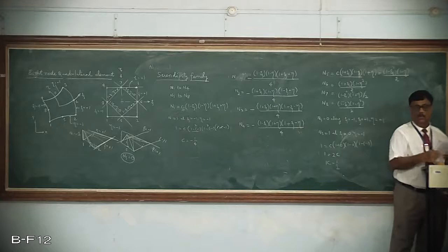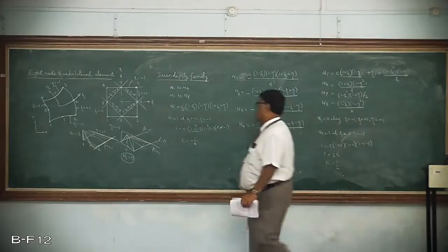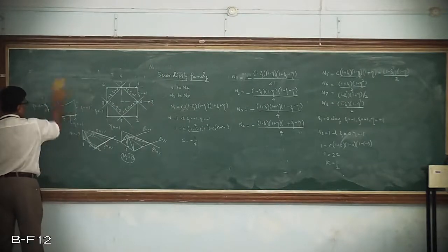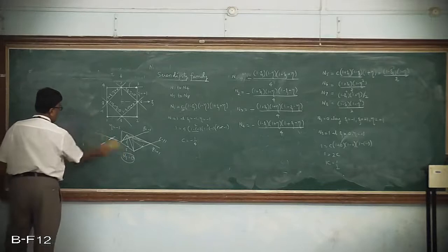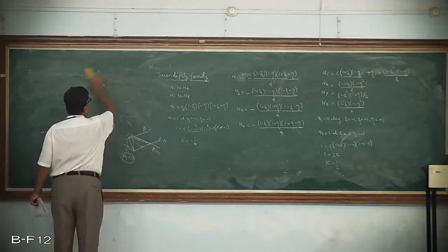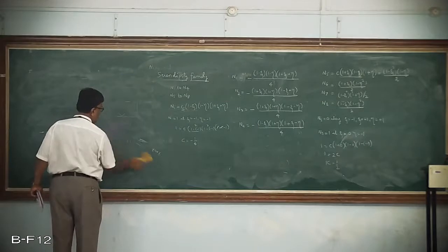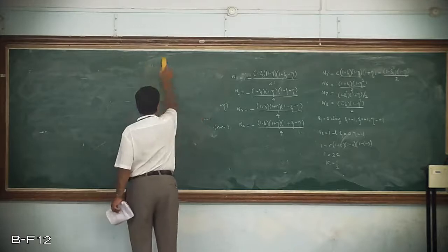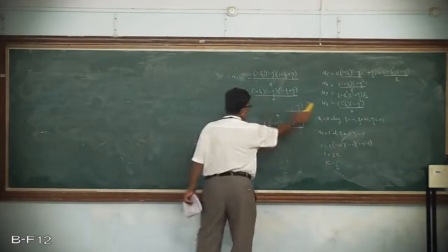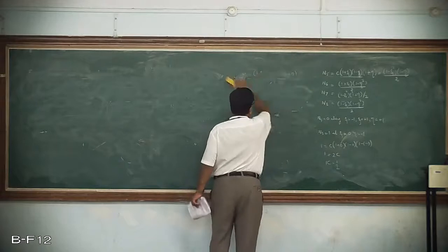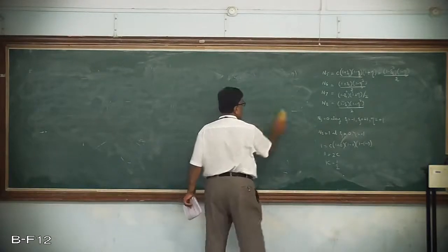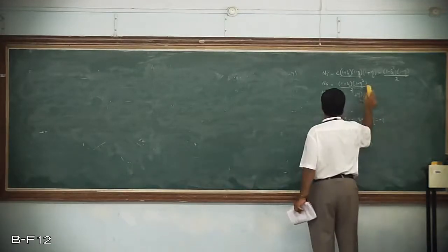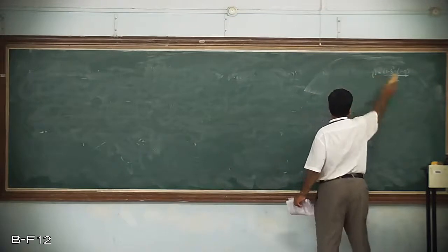It is called 8-noded quadrilateral element, and these are the 8 shape functions. We are separately defining each one of them; first 4 we define separately, and the remaining 4 we define separately, and then we compile all of them. That is how we got 2 different sets of shape functions, which all contain quadratic terms. You can see there is a reason: they carry zeta square or eta square terms, so curved boundaries can be easily mapped using this type of shape functions.